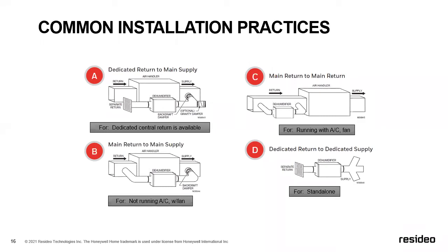One of the things we don't have here, because it would be a whole other pretty lengthy conversation: when we have zoning and we want to do dehumidification, we really have to put that dehumidifier in a design that allows it to be separated from HVAC. That way we're not dealing with trying to understand, well, will this damper be open? Will this damper be closed? What's our static going to be? What's going on with our bypass?